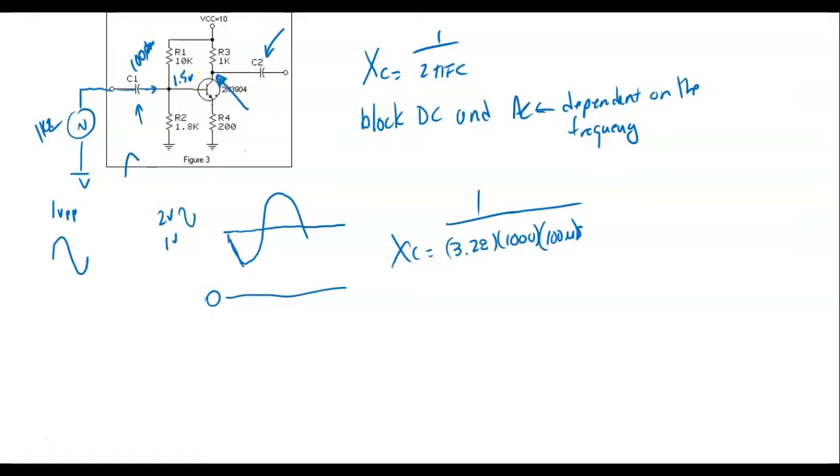But when I couple this out, we want to get AC. So I want to strip off this bias voltage right there and let the AC go out. On the other side of this capacitor, this would be 0, and what we would actually have is an AC signal coming out. So these capacitors, C1 and C2, are called coupling capacitors.